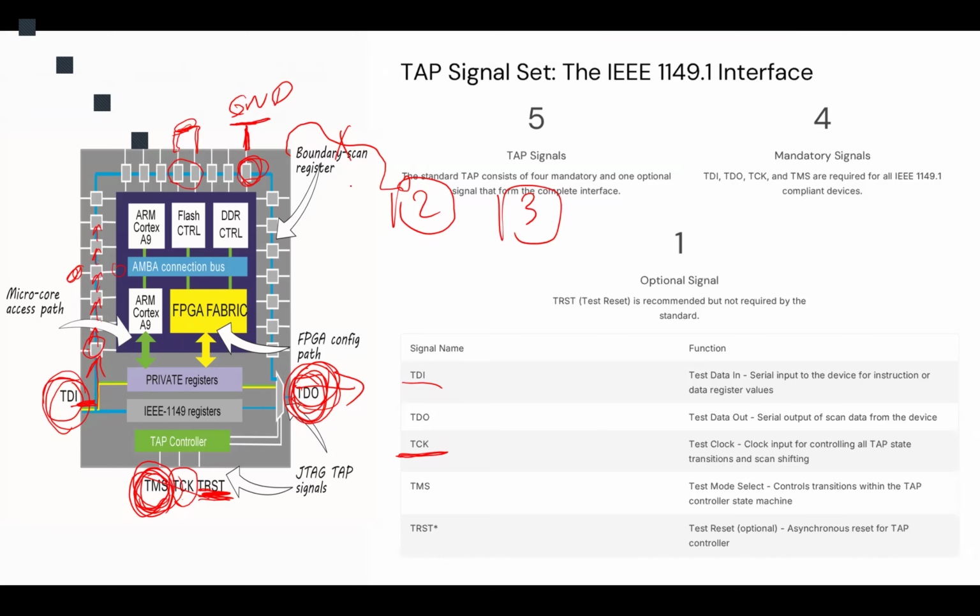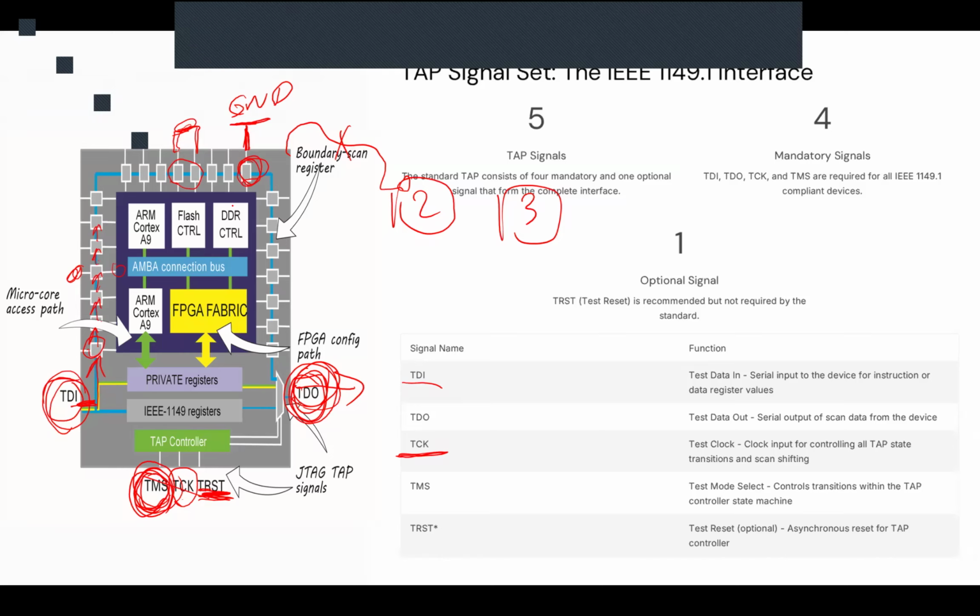So we control when the boundary scan, the JTAG testing configuration, is in testing mode, so there is no output of the core logic connected to the port. Or we are in an operational mode, when we don't inject any testing and all these scan cells are bypassed. So at each pin, we are seeing the output of the core logic.